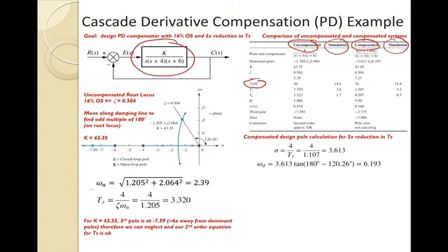So when we did these approximations of a second order system, again, I want to stress to you that these are only approximations and that you really need to use simulation to verify your calculations here. So again, these are all calculations, and the simulated values are shown here. So you'll see the percent overshoot. We had predicted 16, you're getting 14.8, probably close enough. But if not, you may need to tweak the design a little.